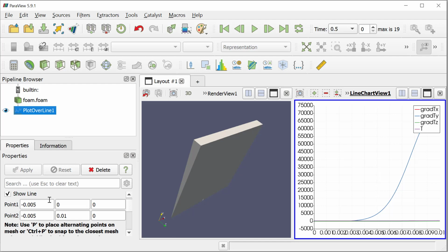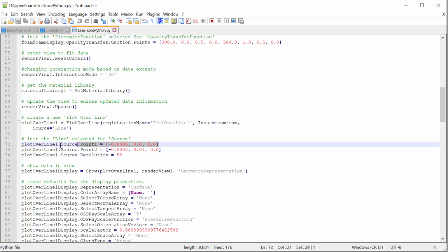So go to your Parametric, and since we force this to be y-axis, now we can look at the points and make sure these points are exactly what's located in here. And then this often doesn't get translated over for some reason either. Just make sure you have that line in there, so that the default is 1000, I think, and you want to be in line with more or less the mesh resolution. So 50 elements, I got 50 points there.